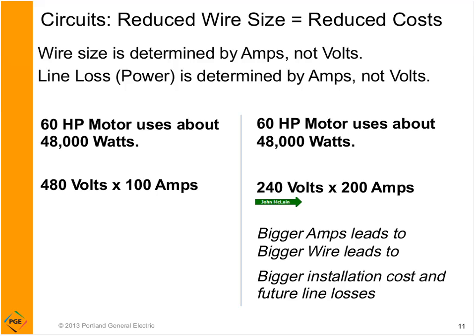So in this case, they found that they could really cut the total installation costs by not just looking at the efficiency of the motor, but by picking one with a higher voltage, so they could lower the amps. So there is a hidden cost that's not on the bill of raising or lowering voltages. So don't buy the 60 horsepower motor on sale just because it's 240 volts, if that in fact isn't going to be made up by the installation costs.